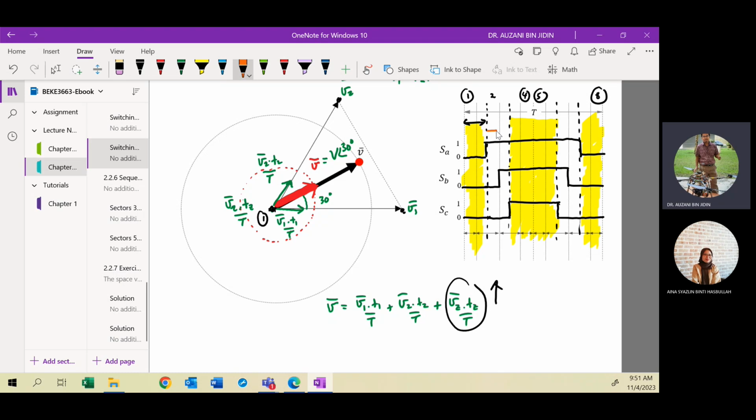So this is for selecting T1, sorry, T1 per 2. You must divide by 2 because you have 2 times: for one sampling period, you have 2 times for selecting V1. Maybe I write T here. So here, T1 divided by 2, and this interval, T2 divided by 2, right?